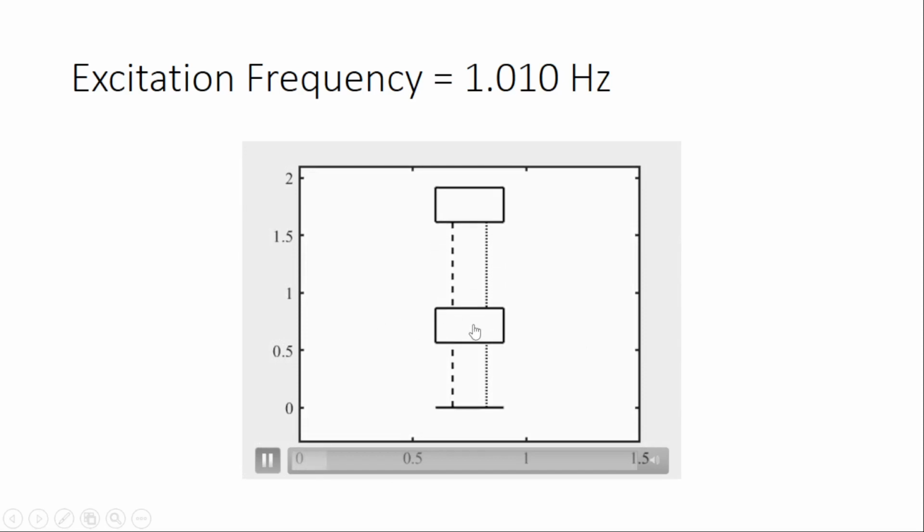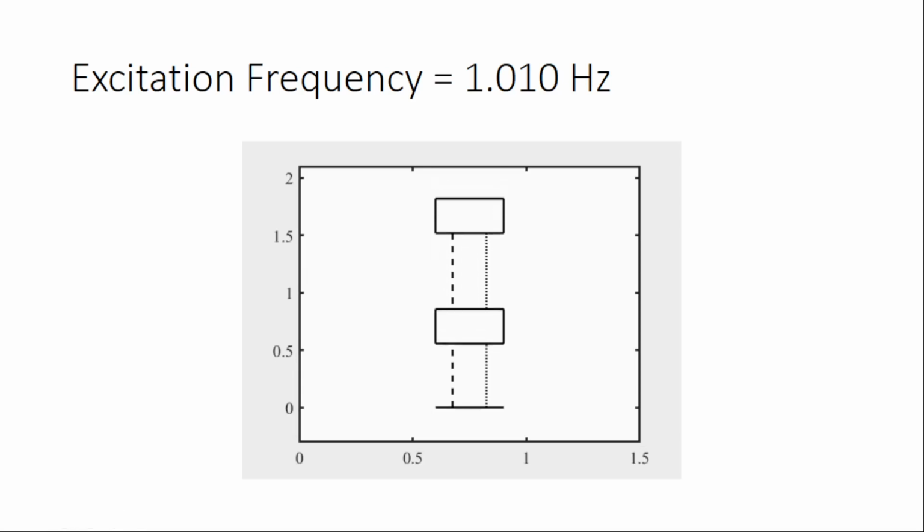this lower mass is oscillating at much smaller amplitude, whereas the vibration absorber is oscillating at much larger amplitude. So that is basically taking away the greater part of the kinetic energy and preventing the mass, basically the machine, and protecting it from high amplitude oscillations.